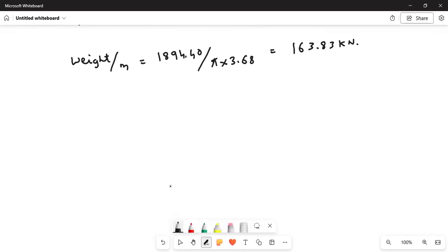And you see, if you take one hopper bottom, this load is acting vertically downward, whatever load you have calculated. And here you have direct tension. So there is a relation between direct tension and the weight. Already we have seen this in our discussion on the design of bunker.